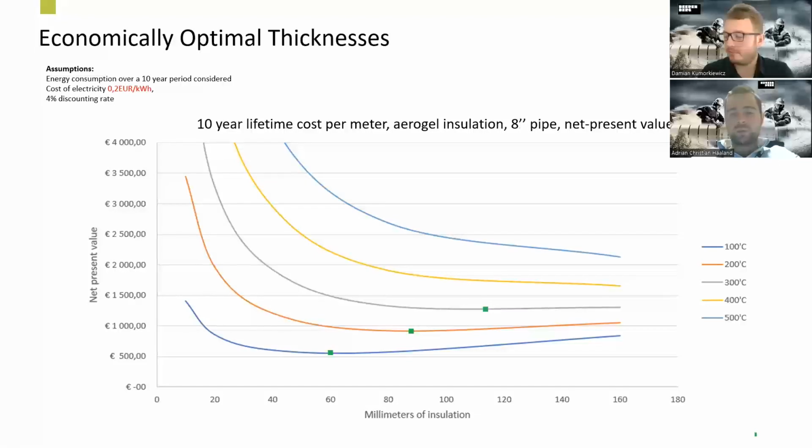And it means, as we've shown some examples of previously, that the cost of the heat losses we see in today's process facility are quite different from what they used to cost. Insulation systems that used to be optimal and cheap in terms of operating expenditure, in terms of operation heat loss, are now costing the operators an enormous amount of money. And when we insulate new equipment, we should factor in today's conditions and not use yesterday's insulation thicknesses.